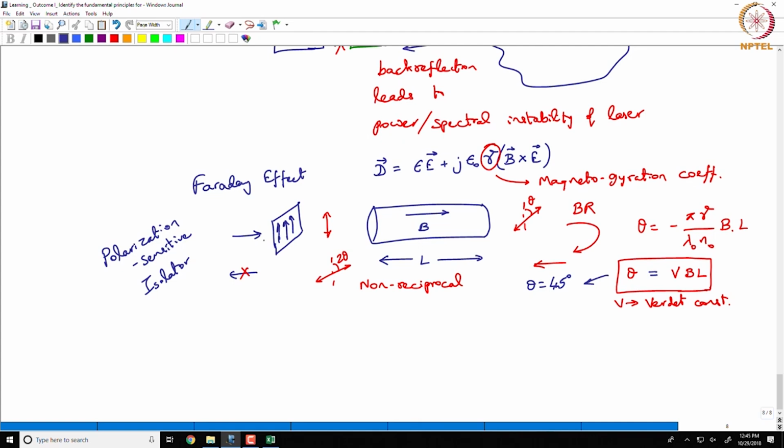If you have circular polarization, for example, coming in, that polarizer right up front would have taken out one of the polarization components. So, half the power would be lost right at the polarizer, the front end itself, right. So, that sort of thing would be lossy. So, what you would need in that case is a polarization insensitive isolator.